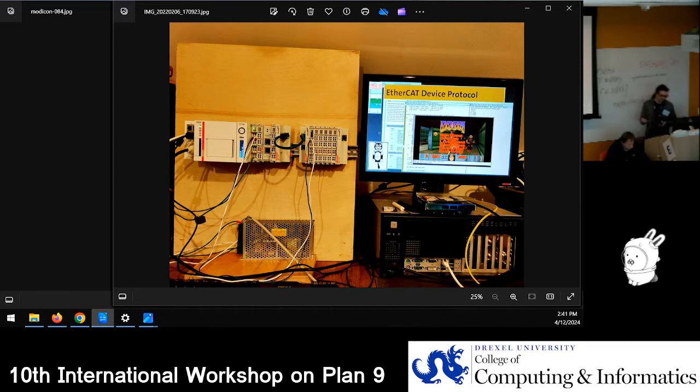So I started out with just this very simple protocol. It's very easy. The frame of it, looks like I don't have the picture of the frame. Darn, sorry. But it's a very simple protocol in which it just starts out with 1 byte that identifies the function code. Then there's usually 2 bytes for parameters, usually like a starting address.